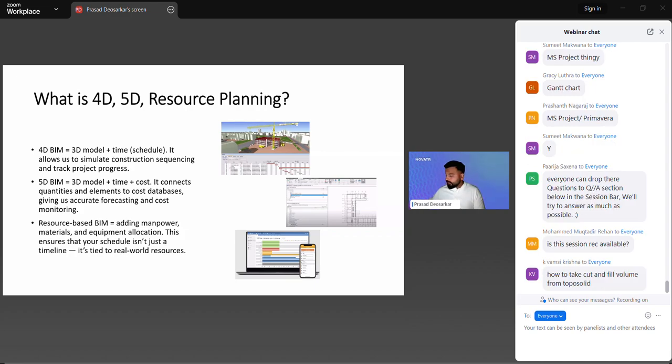So when we talk about ahead of the schedule, let's say 2 months down the line, you are supposed to cast 30 slabs. You can actually do a quantity takeoff now, generate the quantity and order the concrete. You can do a cost forecasting of what will be your budget or what will be your outflow 2 months down the line. Similarly, you can do 6 months down the line, 12 months down the line. The entire project can be analyzed in this way. So at any given time, you can also do a simulation between what was supposed to be spent versus what has been spent on a project.